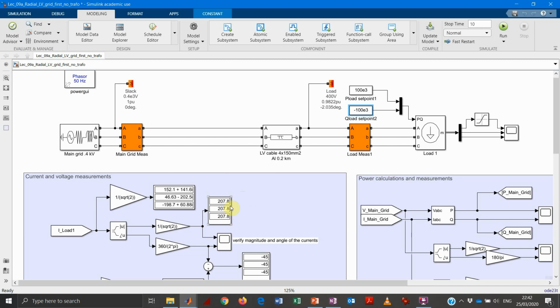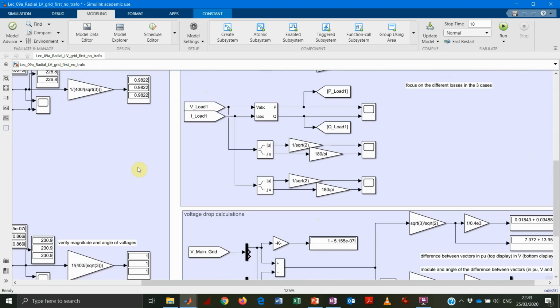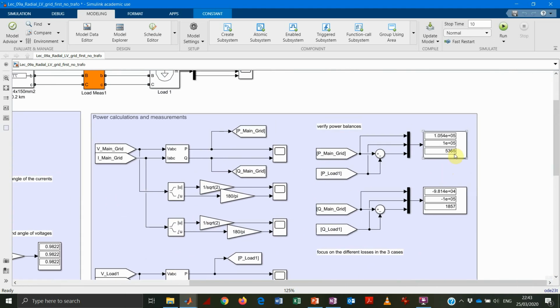The current, even though in terms of complex power this case is similar to the previous case, because I always have 100 kilowatt and 100 kilovolt ampere. The difference is now it is negative, but it's still 100 kilovolt ampere reactive. The voltage is slightly higher. That means that the current will be a bit less compared to the previous case. The angle got minus 45 degrees because the current now is leading the voltage, and I can do again the same reasoning as before.